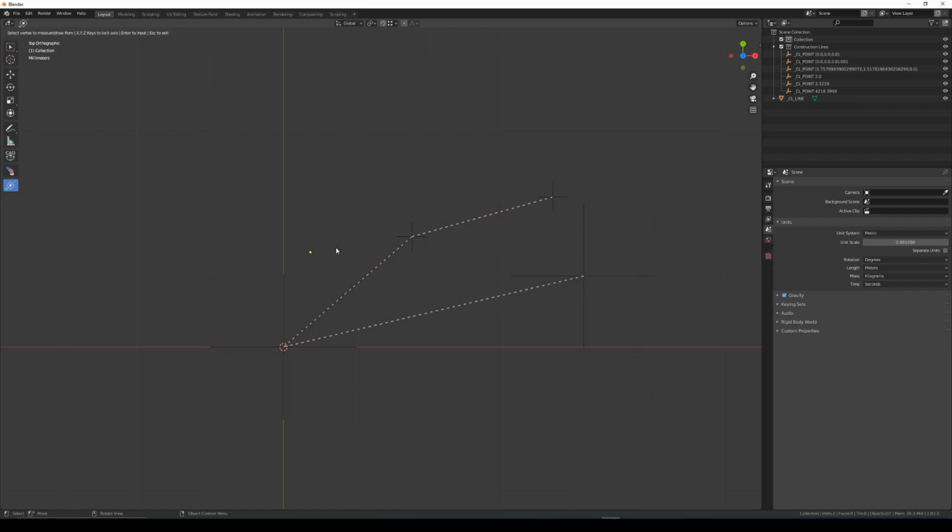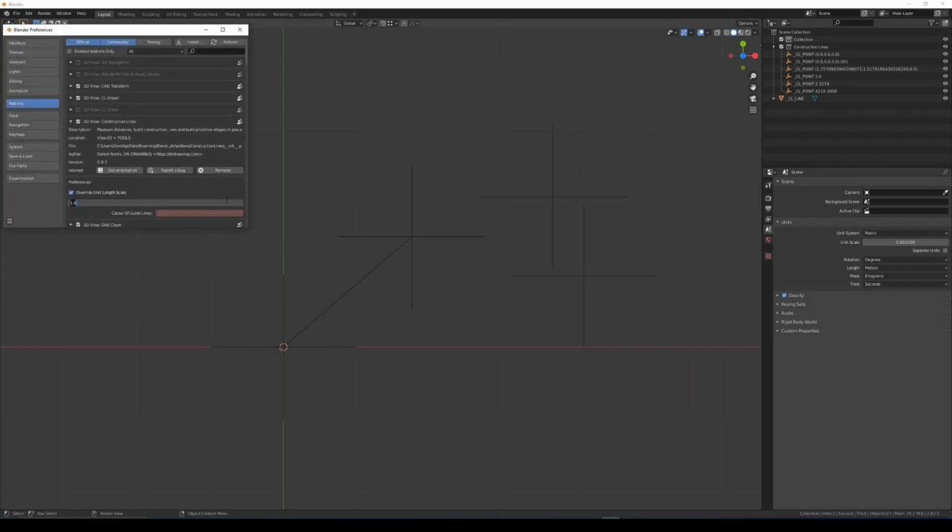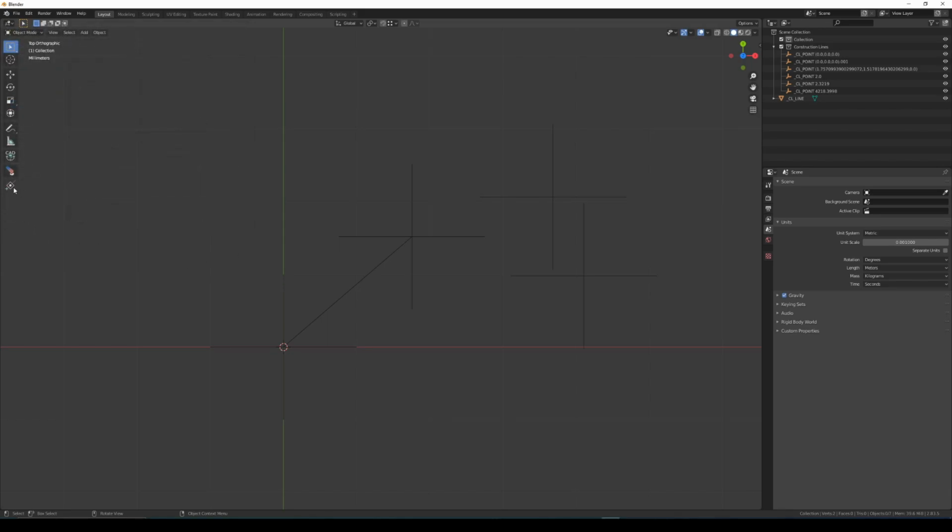And you can also change all existing points. If you right click for the context menu and select Scale All, that will scale everything up to that new scale. And then if I wish to either go back or set a new scale, I might set that to 0.1 for a much smaller guide point.